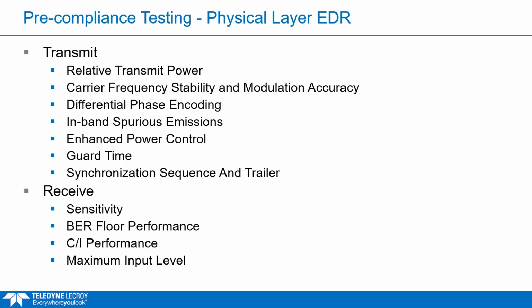And then on the EDR, extended data rate, again, that has tests on the transmit and receive side. So you can see here, you're going to cover power and sensitivity type tests, but there's also some EDR specific tests, such as differential phase encoding and guard time.